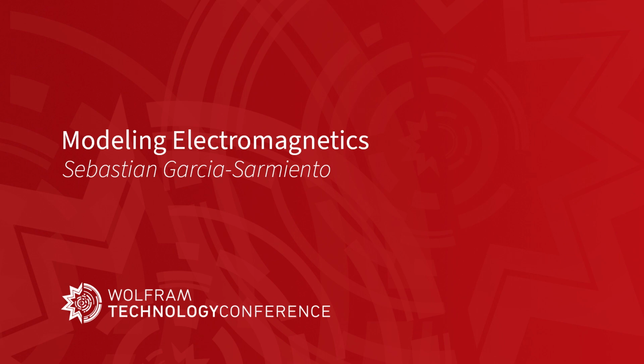So basically, electromagnetic fields in 3D cases, most simulations done in 3D domains will be really difficult, because you need another kind of element in our current version of the finite element method in Mathematica. There can be 3D models that you can simulate, for example with magnetic fields, if you only want to simulate time-varying magnetic fields. But the coupling between electric and magnetic fields in the electromagnetic, high frequency regime is not possible right now. So we already have these limitations, but we are working to extend this to more things in the high frequency regime.